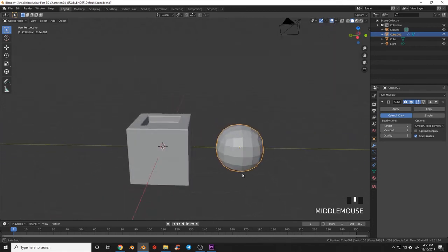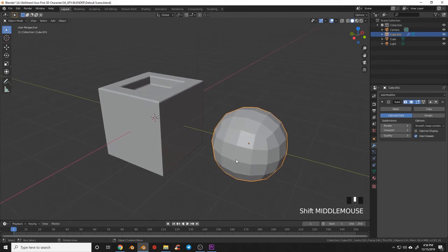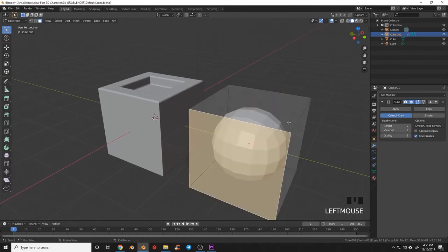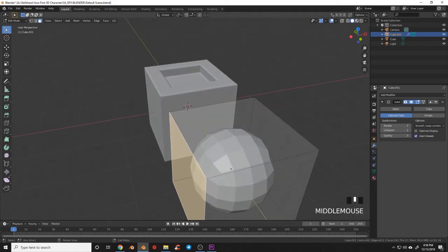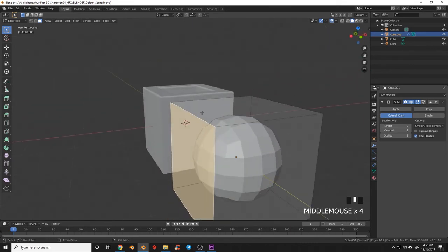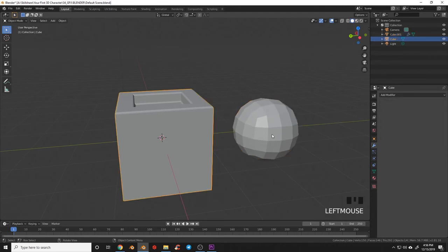So let's look at how subdivision is affecting this model, because it can be kind of difficult to understand at first. What it's doing is subdividing from edge to edge and then trying to create a smooth subdivision from there. We've told it that we want it to subdivide to the power of 2, and that is going to divide this twice, giving us these 12 faces on top, and then it is trying to blend from edge to edge. Now let's see, we end up with a kind of sphere looking shape.